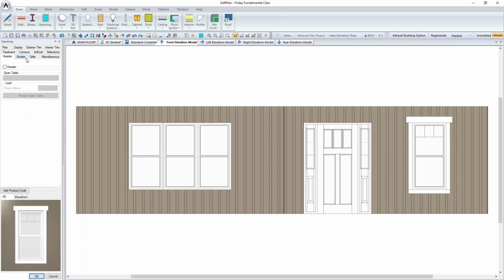Everything that you draw, again, you're drawing towards a bill of materials. So your header spans by default on an exterior wall are going to be 2 2x10s. You can specify and change it depending on where you're building and so on. Other things include the soft list, which is a bill of materials item, and res check for those of you that are running res check on your openings.